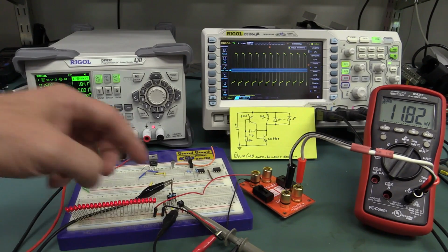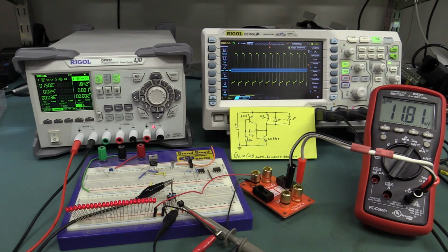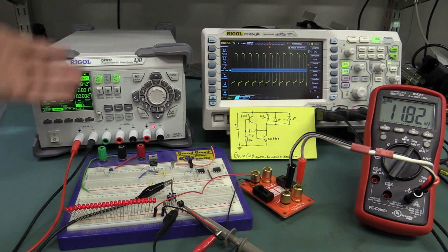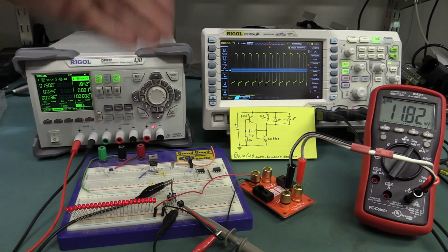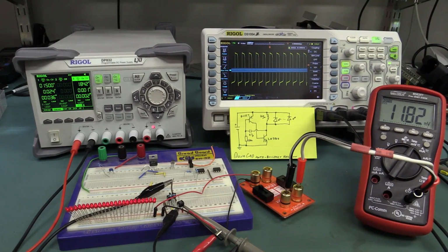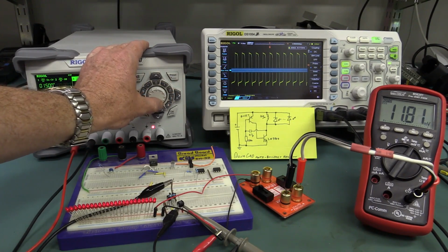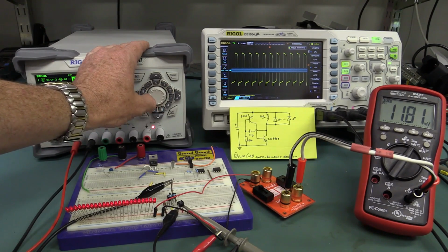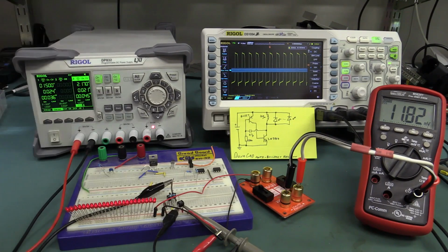So no problems whatsoever. There's no magic core happening here. I'm just using an off-the-shelf SMD inductor in there of 100 microhenries. No worries, I can power 23 LEDs, the poorest LEDs I could find. They're absolutely horrible. Even at 20 milliamps, the damn things are absolutely useless. There it is at 20 milliamps. That's how bright they are. They're hopeless LEDs, and it's fine.